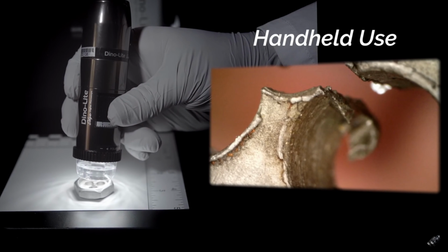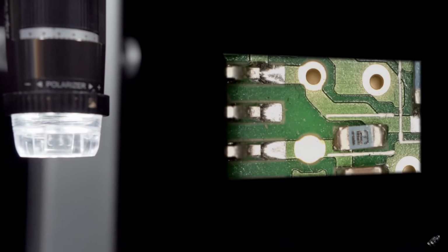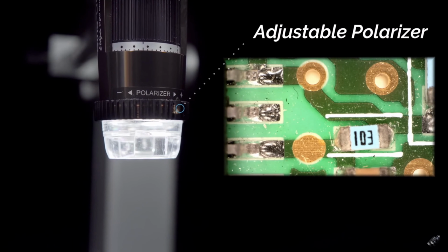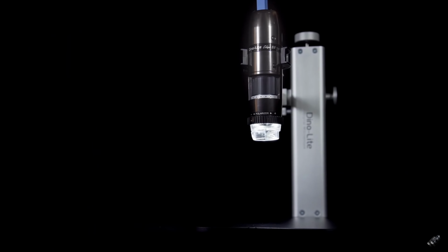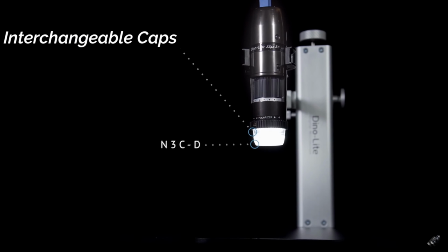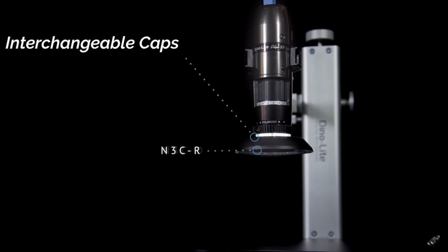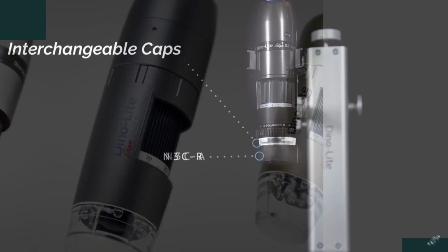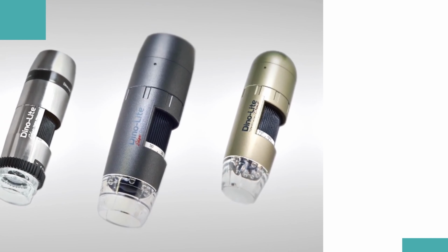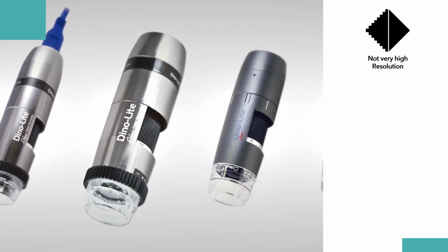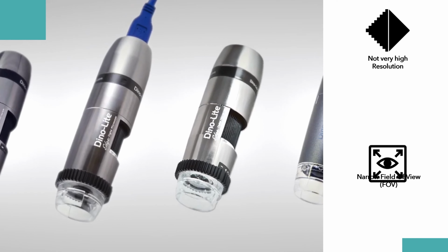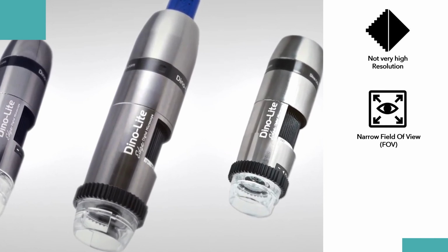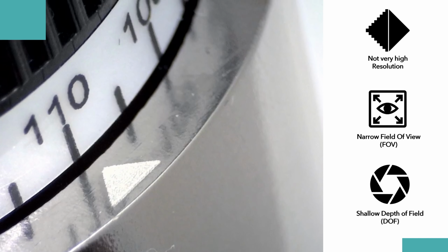The challenge is configuring a highly performative micro-photogrammetric system using the now low-cost and widely available digital portable microscopes. This will imply testing their validity on microscale survey, overcoming operational difficulties, and considering the limitations which could compromise close-range photogrammetry: not very high resolution, no wide dynamic range, narrow field of view, and shallow depth of field.